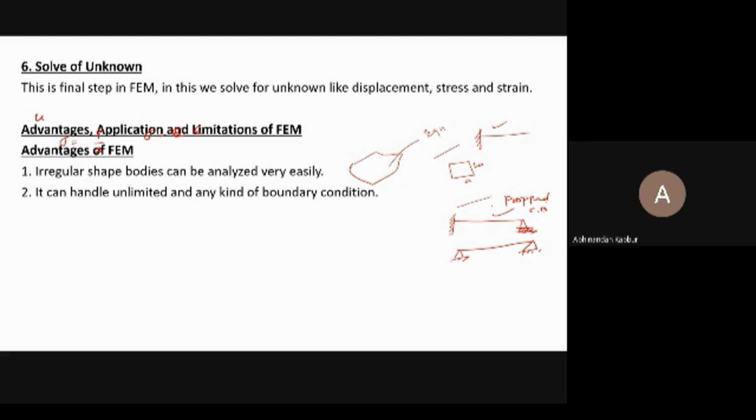Are you following this? Suppose it is applied with the force P. How are we going to find the reaction? How many reactions are there in this problem because of this applied force? Yes, three reactions. Because of this applied force, at the fixed end I have R1, and at this end I have R2, and I have a moment reaction M1.